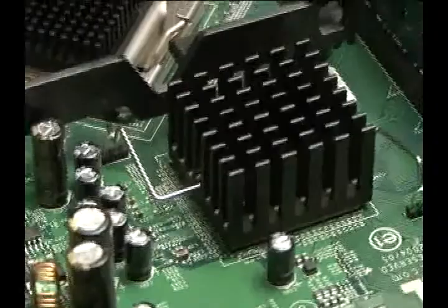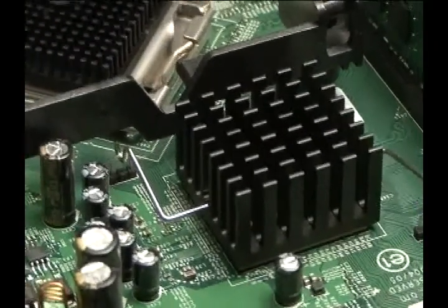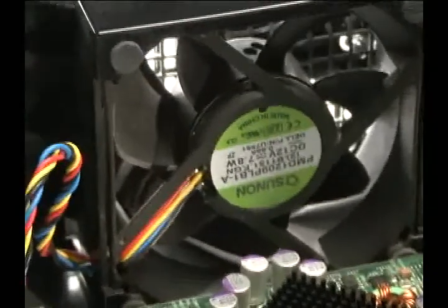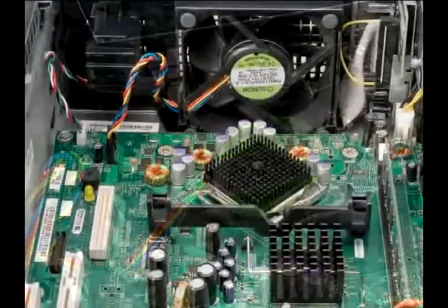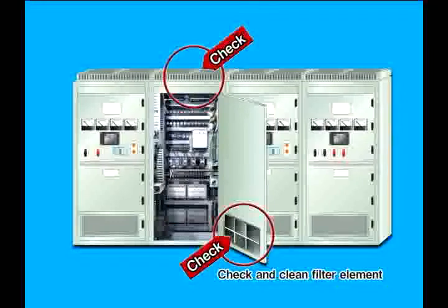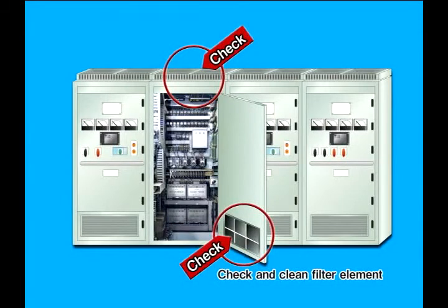Because of its properties, control over the semiconductor device can be lost, resulting in malfunction or breakdown. It also generates heat during use. A heat sink and fan are used to prevent the semiconductor device from overheating. To ensure the maintenance of a low ambient temperature for semiconductors, it is important to periodically check that the fan is working properly and that the panel intake filter is not blocked with dust and oil residue.